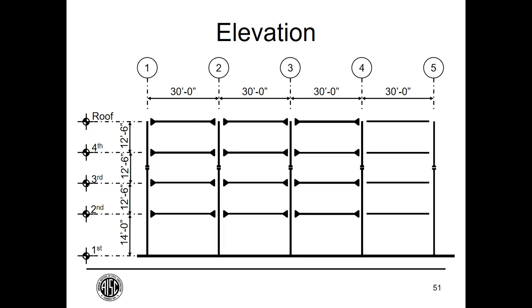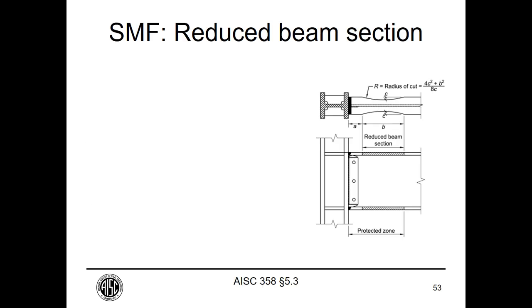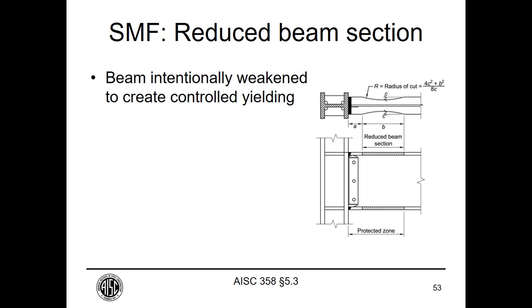Here's an elevation of the moment frame. Seems perfectly fine. We have 3 bays, 4 stories tall. And the buckling restrained braced frame looks like this, just 1 bay, 4 stories tall. You probably expect a fair amount of overturning in this configuration. The important decision early on with moment frames is to determine what the connection is. And the reason for this will come clear in this list.